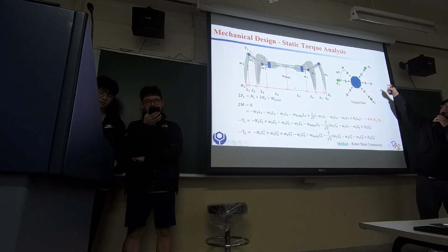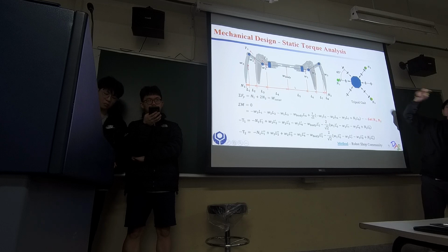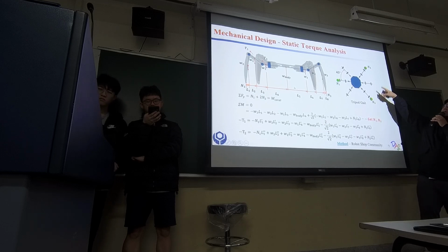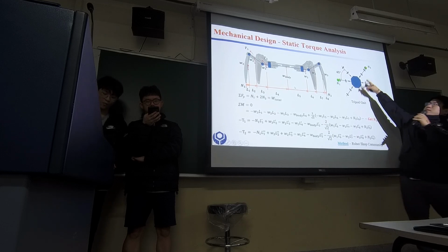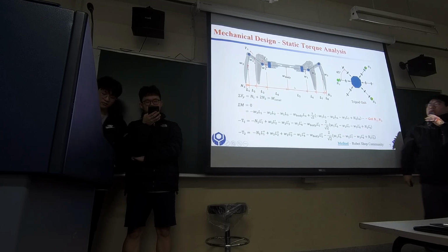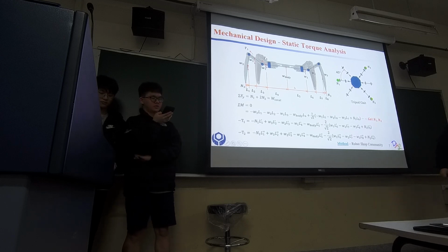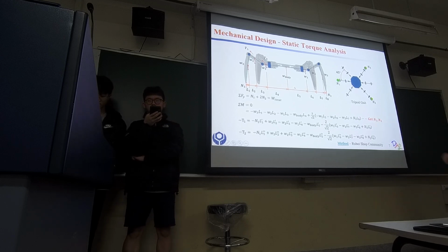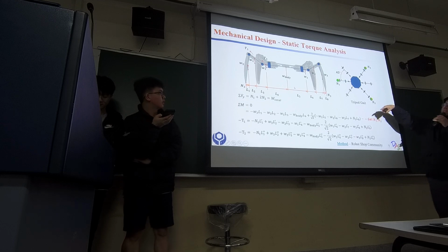In this situation, we use the tripod gait to guide our robot. The tripod gait means every time we move 3 legs. You can see the blue set will be moved together and the red set will be moved together. There will be two gaits.